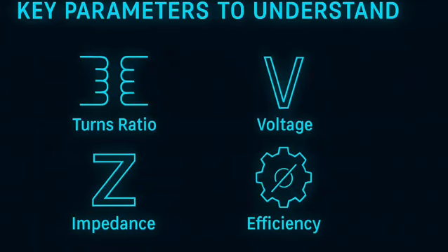So in summary, as a parametric comparison, just to revise: primary voltage is important from a safety and insulation standpoint, and the alternate is allowed to differ only on the higher side. Secondary voltage is a functional requirement and should be the same. For turns ratio, output consistency should match, so the turns ratio value should be matched.